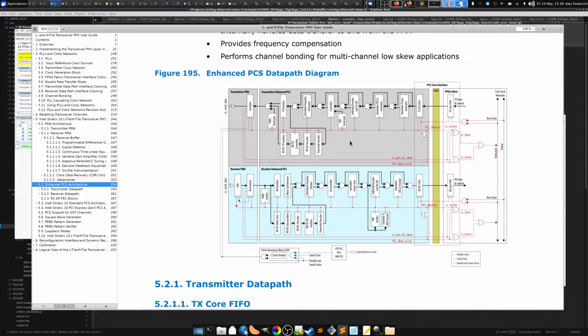There's one of the major differences between the Intel components and the Xilinx components in terms of the serializers: the Intel ones actually have a lot of additional hard logic for supporting various protocols. They also need additional hard logic to support the EMIB interface. What's not shown here is that there's an AIB block on both sides of the EMIB that you don't actually see because it's buried inside of the IP core, but it is there. So in the transmit direction, you go through a FIFO, then AIB, then EMIB, then AIB, and then another FIFO.